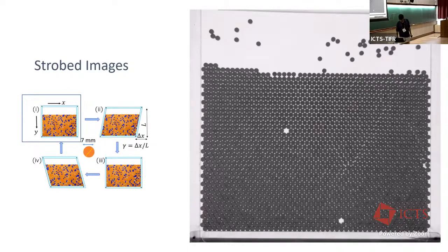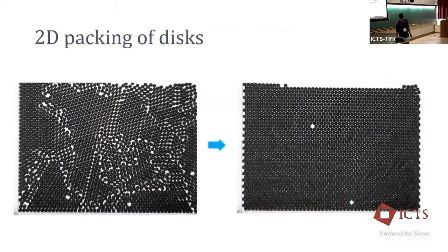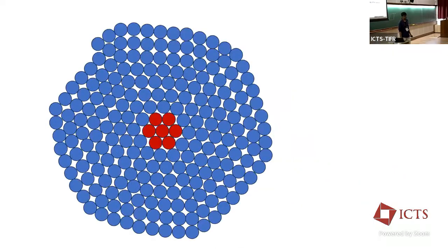Remember, just for fun, if I had shown you the way I was packing up here, randomly making errors, you did have square lattices. If you look here carefully, you will find that there are some places where there are patches of square lattices. Typically, square lattices will not be there in the system. But as you start getting defects, you can have gliding defects, and there you will have one exactly on top of the other, which will give you a square lattice, locally.